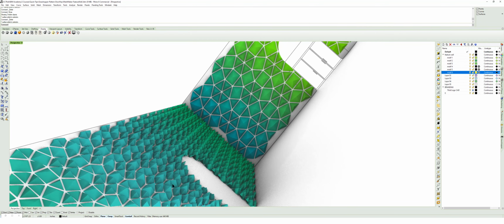And now pulling that centroid point to my surface, I'm now going to get the UV coordinates of the point to the surface. Okay, and those UV points are essentially a percentage. Because we reparameterized this way back at the beginning, that's giving me some percentage of 0 to 1 rather than a length dimension. It's actually some percentage. So no matter how big or small this surface becomes, it'll always be some percentage. Okay, plugging that U and V into the UV coordinates.